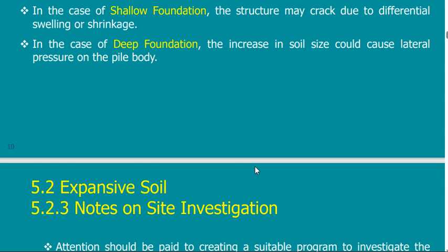Yani, you don't have swelling soil and you tell me that I'm going to use a raft. Swelling soil, the soil wants to increase and you are putting a big raft on top, so you are not giving the soil a chance to increase in volume without affecting your structure. So there are some wrong choices, so you have to know this by heart.